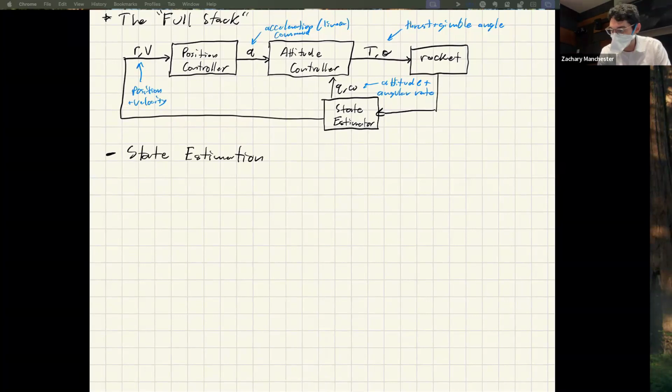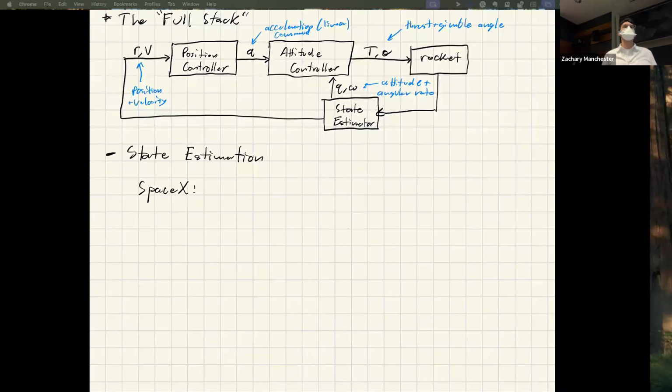So for the SpaceX case, it's basically just GPS. Those landing things are terrestrial scenarios. You have GPS, and the GPS receivers, if you use high-end stuff, you're basically fusing GPS with an IMU. That can get quite good, actually. You can get very, very good velocities out of those. And if you design the GPS receiver and you do the inertial fusion with a good IMU well, you can get down to meter level positions pretty easily, even better if you're really good.